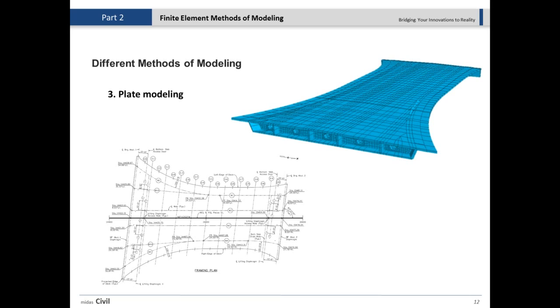So with this type of geometry, what do we have to do? As Andrew mentioned, there are a couple of ways to handle this type of geometry. We can either use beam elements and model it with the grillage model, or we can also model them with plate elements. Each one has its limitations and advantages, which we're going to discuss today.